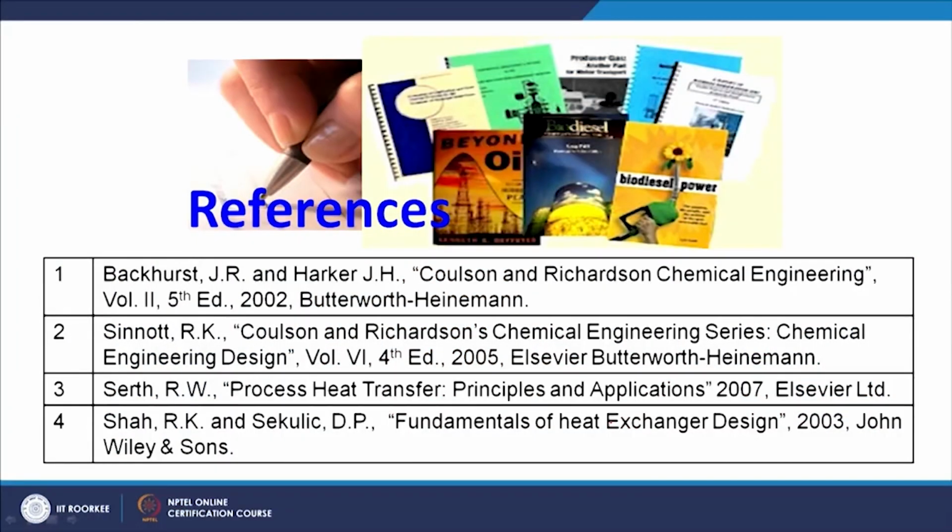So, in a common heat exchanger like the fixed tube sheet, you can put the exit nozzle at the rear side also. So, there we can have an odd number of passes also, but usually we consider inlet and outlet at one side only, and therefore the standard we follow is to consider an even number of passes in tubes, right. And here we have some references which you can go through for details of the tubes.